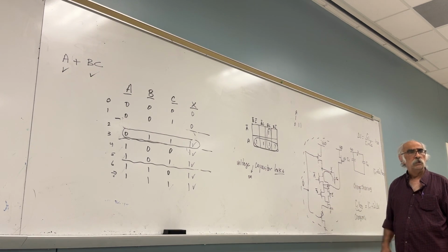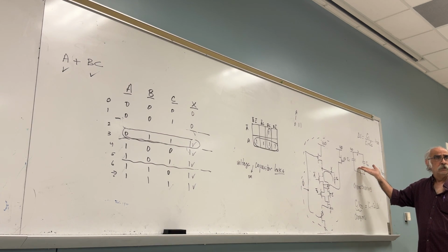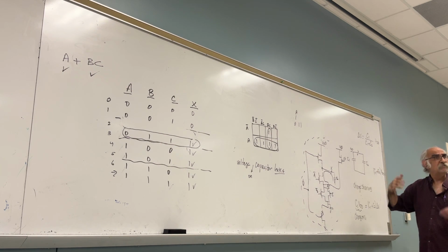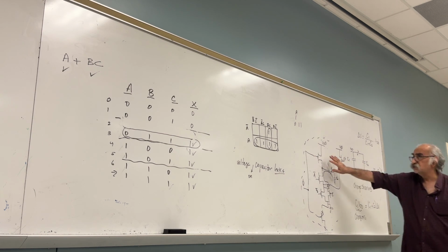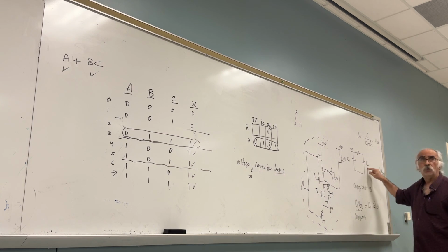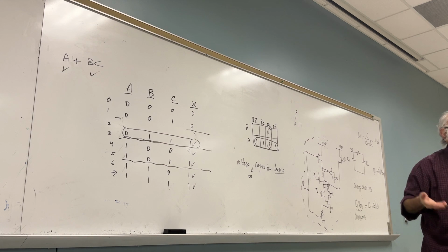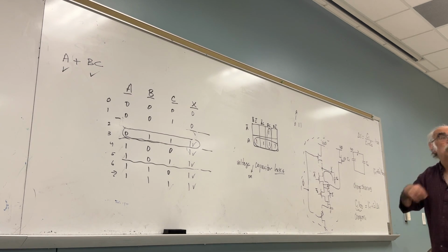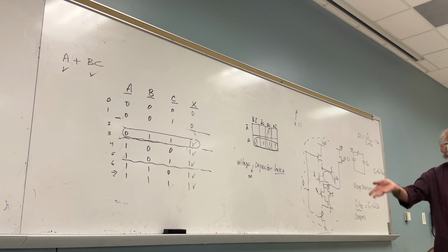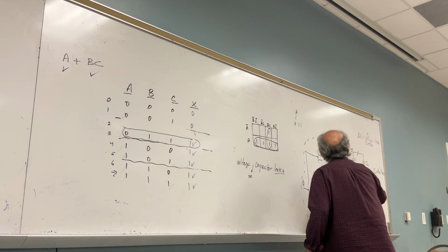No, without pre-charge. If you don't pre-charge, you have this case. But because the source of the NMOS is not at ground. Doesn't matter. What I'm trying to tell you is that if you are not going to pre-charge all the nodes, only this one, then C1 and C2 will have different voltages. Okay. They are different voltages. You agree? But you said they'll charge share to the same voltage. This is with you just telling me do not pre-charge all the nodes. Didn't you just say that? Which means what? Remove this.